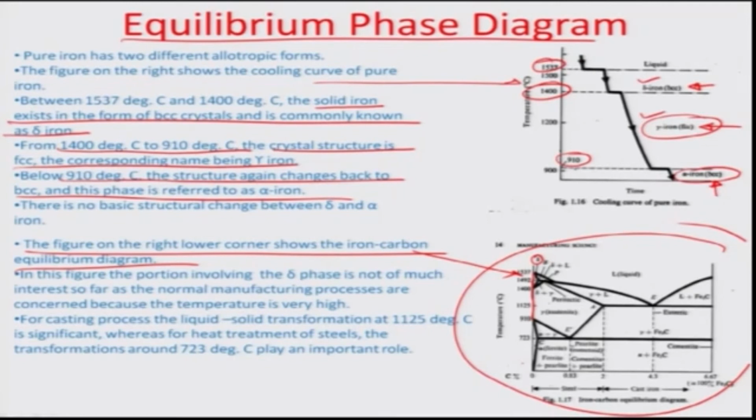So, you have three different structural constitutions of the iron, and then obviously you have a solubility of carbon varying between 0 to 6.67% right here, where in one case it is complete cementite, Fe3C 100%. This corresponds to only 6.67%, beyond which the iron cannot dissolve the carbon. So, below this there are different phases. In one half the strength of the iron increases very highly up to 2%, and beyond 2 and below 6.67 this is actually the cast iron phase.